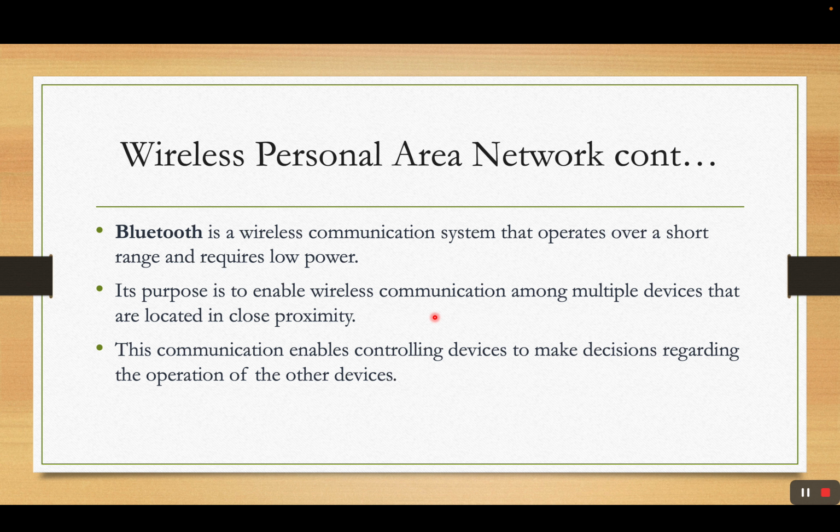It's a very low power RF, radio frequency, technology. It supports TCP, UDP, and so on. It supports star topology, point-to-point topology, and mesh topology. Low energy Bluetooth based mesh technology is a new standard for expansion of IoT based networks of devices.